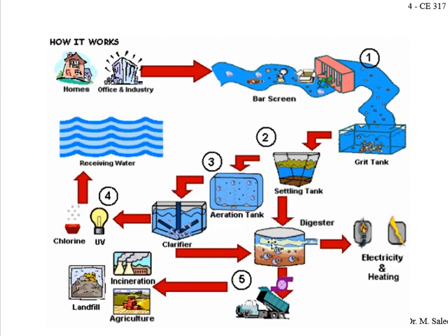They eat that one and they produce the methane gas. This gas is useful for us for generation of electricity or for getting as a fuel. We can use it, and the remaining solid we can use as fertilizer for putting in agriculture and other places, or you can throw it into the landfill or the incineration. So this is a complete setup of the wastewater treatment.